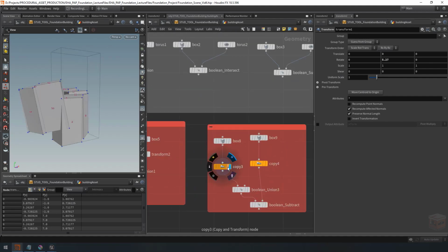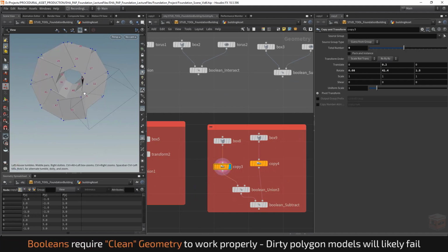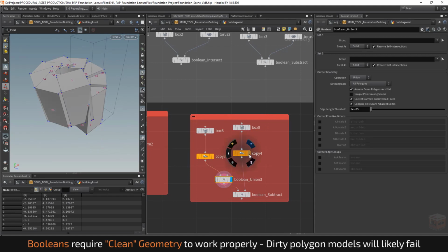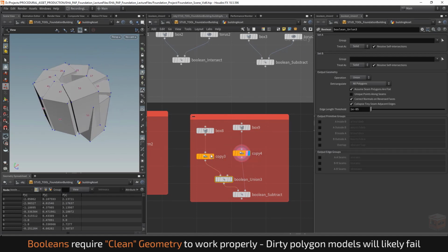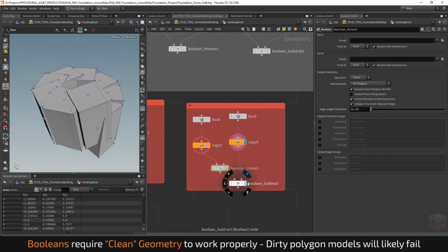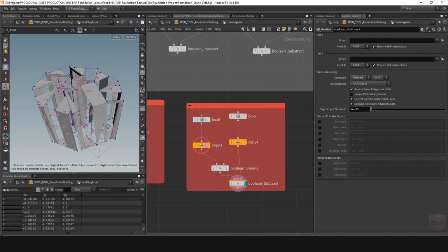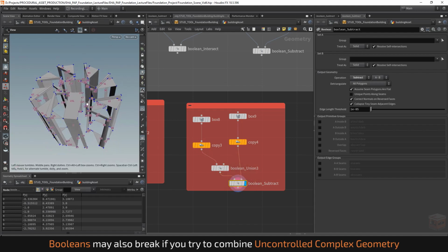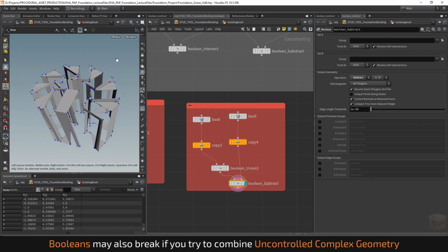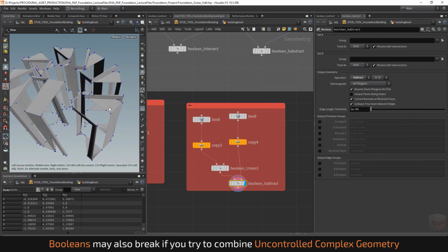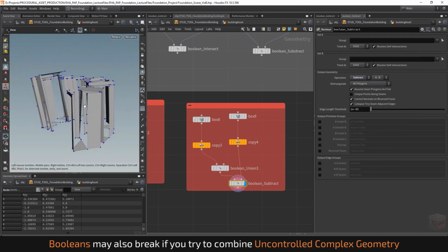Likewise, if we take some very complex geometry, like our little custom torus over here, or staircase, whatever you want to call this, and then we Boolean that, and then we take another one with a slight variation on it, so like this basically, and then we try to say subtract one from the other, well, it's going to cause some bad geometry as well. And in this case you can't even see all of it because I have my back faces turned off. Let's turn them back on. Now here you can see we have some Z fighting going on. We have some very thin pieces of geometry.